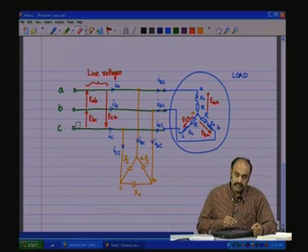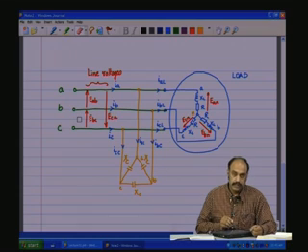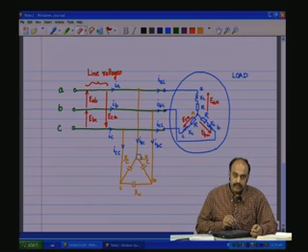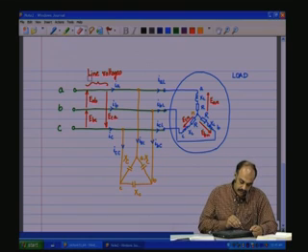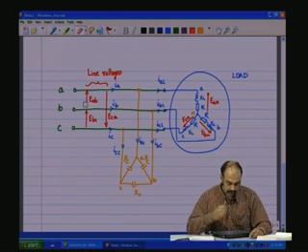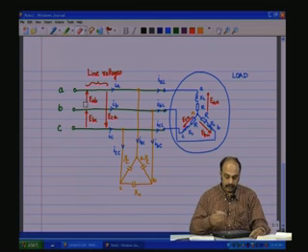Therefore, to compensate for the reactive component, so that it can be delivered to this buffer capacitance and taken in as and when required, the capacitive reactive network as shown here is generally used, so that the power factor as seen from the source side is improved. That will become evident once you look at the phasor diagram.